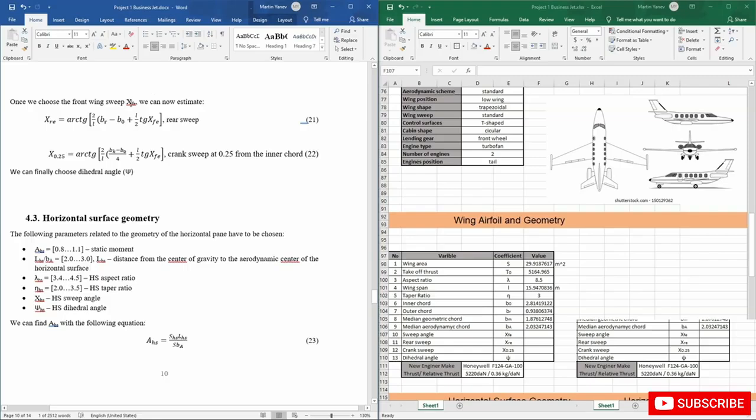And normally, the aircraft that are traveling with transonic speeds are having wing sweep of about 10 degrees, and actually this is the degree that I'm going to be using. And you should know that the more speed the aircraft produces, the more sweep it needs, okay? Because that really helps for the aerodynamic characteristics on high speed.